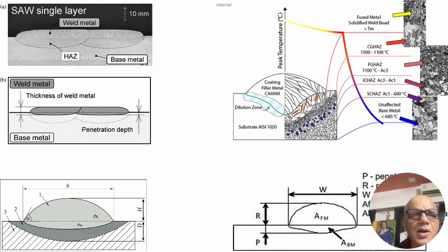And the weld bead with the penetration pattern, if it is so deep, then the dilutions are going to be very high, because this is what is going to be the diluted material, and we want the bare minimum dilution from the parent metal to come. So we may use a little higher arc length for overlay, which we don't use in our butt joints, because there we are concentrating more on penetration.